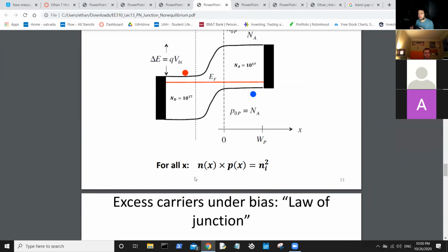When you're asked to solve for resistivity at equilibrium, it's traditionally in one of two places: in a neutral region, whether that be P or N, where it should be the same in either one, or at the junction point. Most of the time it's probably going to ask for the junction point because that's the more interesting solution. So at equilibrium you need two formulas: the rho formula I just said, and n times p is equal to n_i squared.